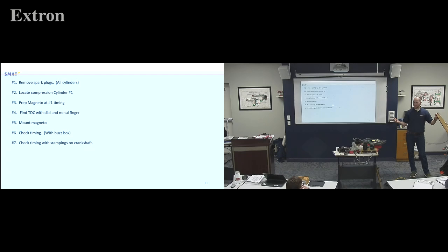Now, here's where the differences get. Some people would say, you already found it. Go ahead and take the finger out. When you get back to top center, you're top center. The problem is, if you messed it up, you won't know you messed it up. So the Case Visser way is, come back around and make sure you did your math correct. This should hit at 40 again. What's it say? Yes, 40. I did my math correct. So that's just a sanity check.